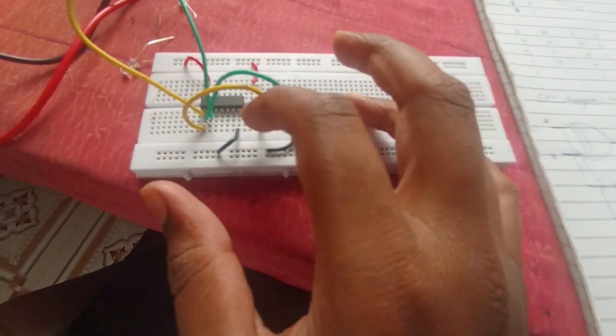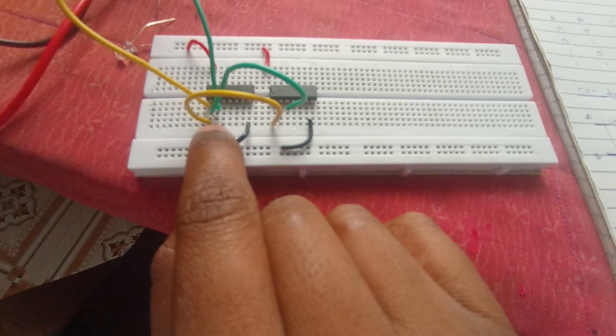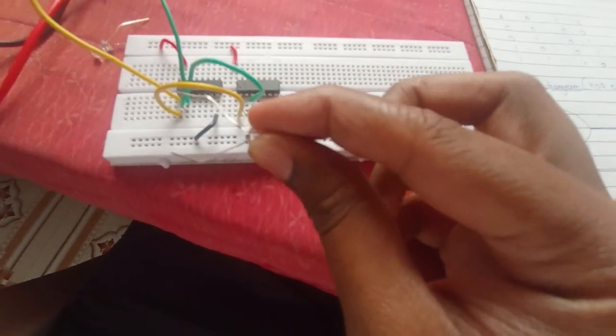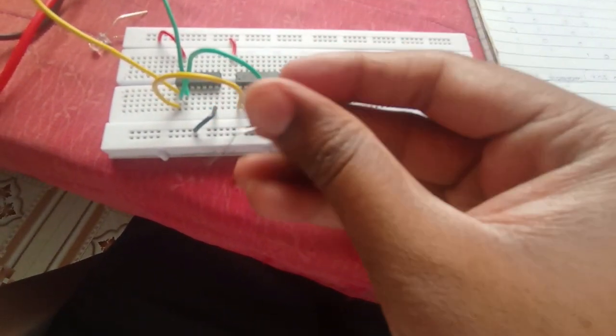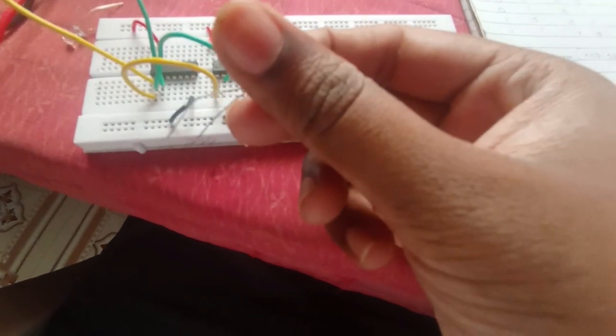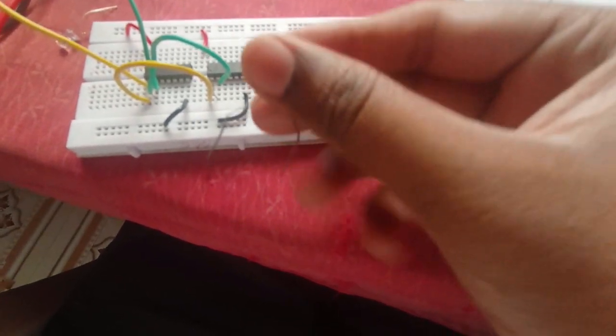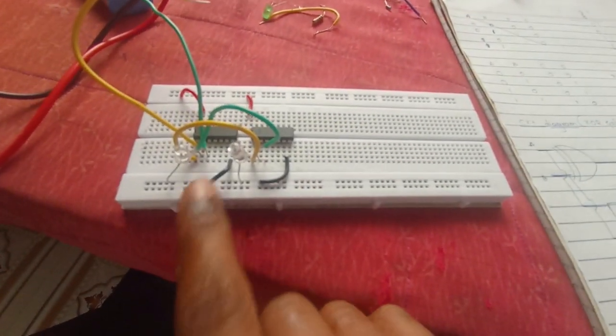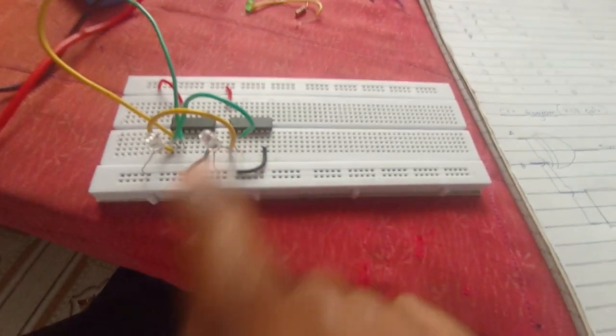Now you have to connect the LED at the third pin of both ICs, for the output of sum and carry. I'm going to use 2 LEDs of this type to connect to the third pin. The third pin is connected in this format. The longer lead of the LED must go to the third pin and the shorter must be grounded. The longer lead is positive and the shorter lead is negative. I have already told in many of my previous videos that the long one is positive and the short one is negative. So let us connect the LEDs. I have connected the LEDs at the third pin for both ICs.